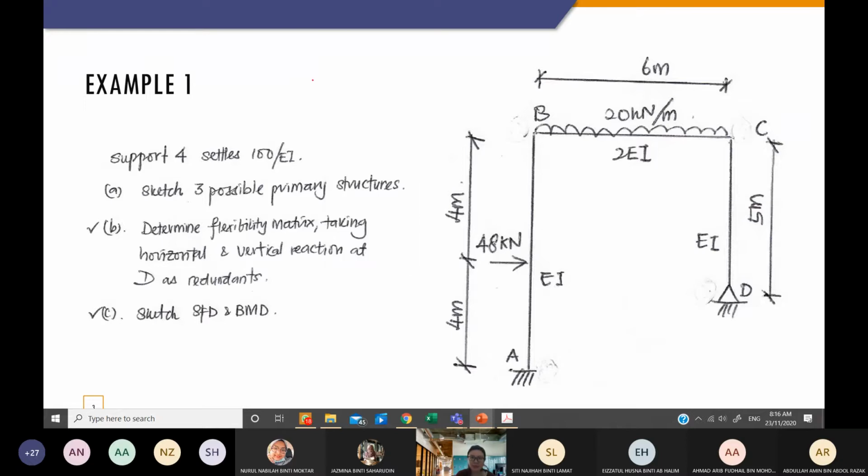It will be just using the equation similar to beam. Okay, so what we have is R minus N minus C. So how many support reactions in this case? Anyone can help? Five. Thank you. And N will always be 3. No C in this case. So we have 2 degrees of indeterminacy, or we have 2 redundants here.